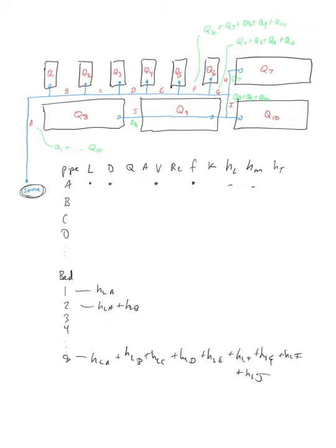Part of what I mean by that is, if we think about what's actually happening here, we've talked a little bit about parallel pipes before, right? We have a pipe and we have two branches that go to the same point and then continue on. And we've said that the head loss in this segment right here is equal to the head loss in this segment right here. The flow rates in each branch are not necessarily the same, but the total flow rate entering each junction is equal to the total flow rate leaving each junction.